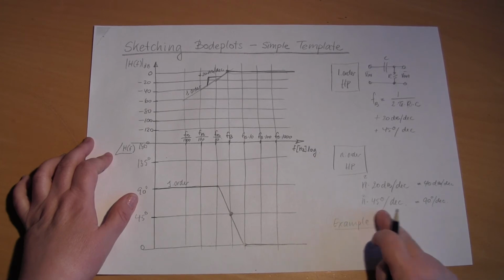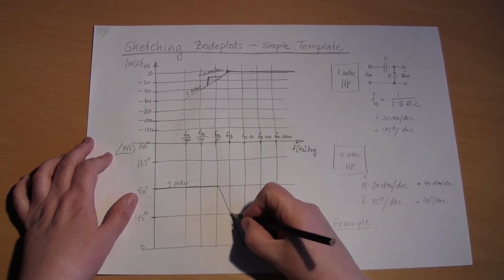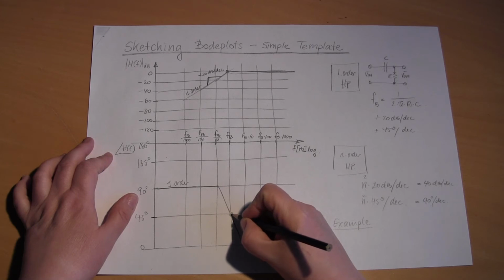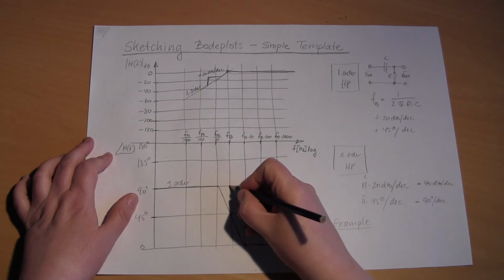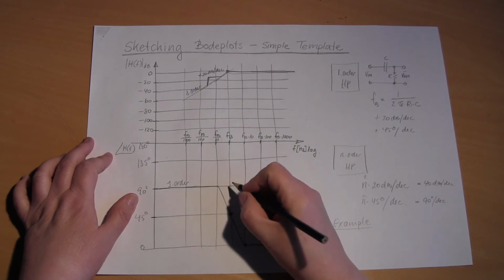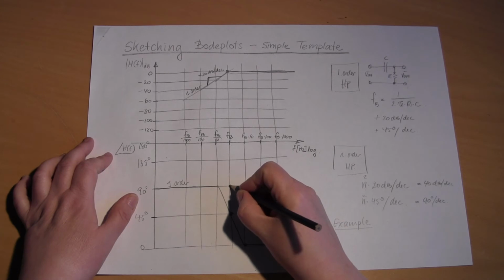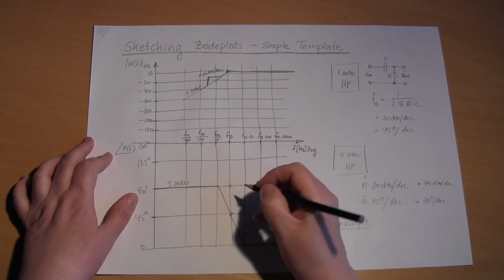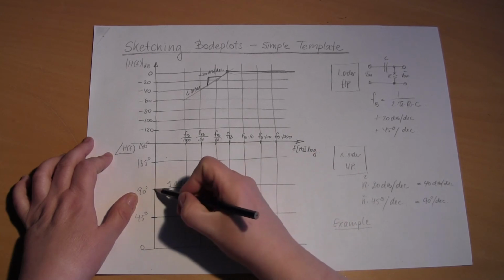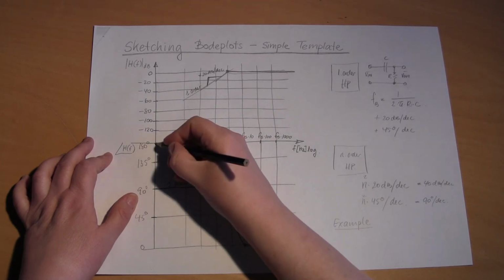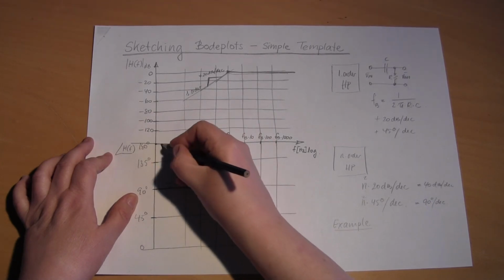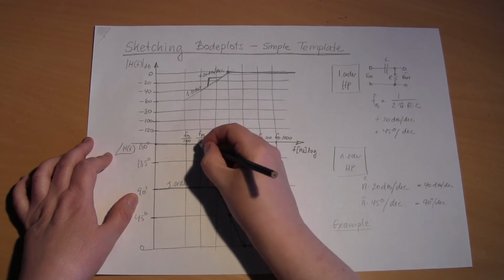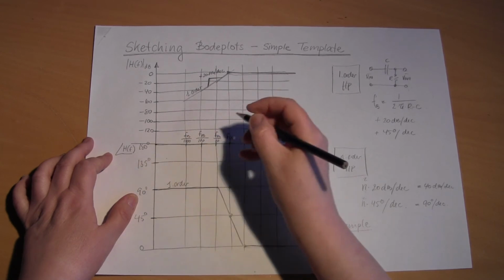That means also a change to the phase shift, because when I have the second order, I will have twice as much phase shift in the breakpoint. So that means I will actually at the break frequency have 90 degrees phase shift. Also at lower frequencies I will have 2 times 90, so I will actually be up on 180 degrees for a second order high pass.